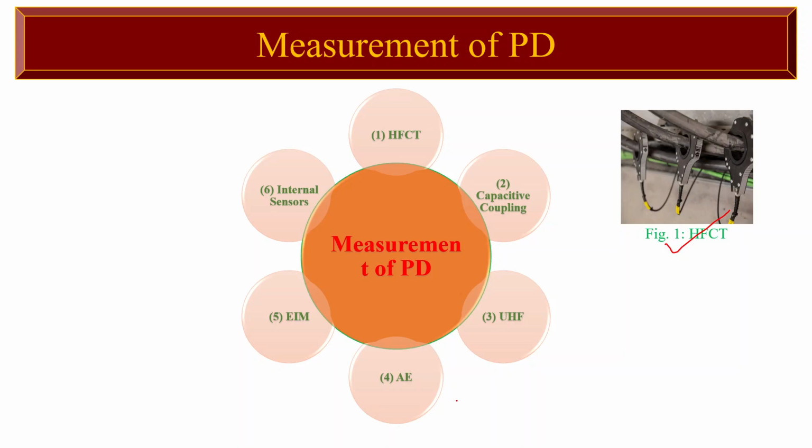HFCTs are widely used in various applications, including power cables, transformers, switchgears, and rotating machinery. They are particularly useful for online monitoring and condition assessment of electrical assets, as they allow continuous measurement without the need for a shutdown.